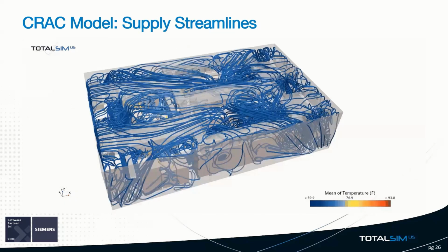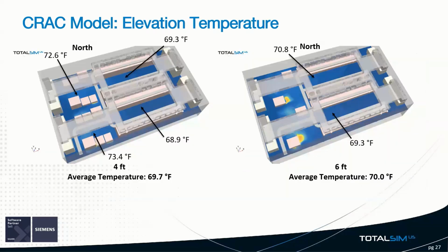This shows how the cooled airflow from the HVAC units are moving throughout the room. You can almost see the 2 cold aisles in front of the server cabinets are overcooled. Looking at the slices at 4 feet and 6 feet, anyone walking through the room will be comfortable.